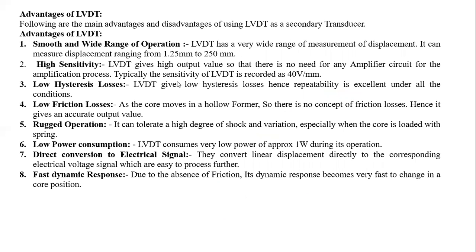The advantages of LVDT. The first advantage is smooth and wide range of operation. It has a very wide range of measurement of displacement. It can measure displacement ranging from 1.25 mm to 250 mm. It has high sensitivity; the sensitivity of LVDT is 40 volt per mm.